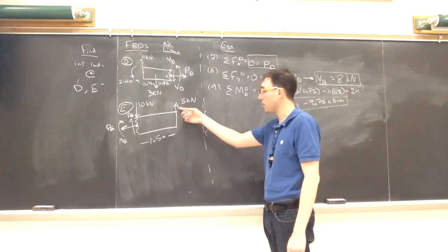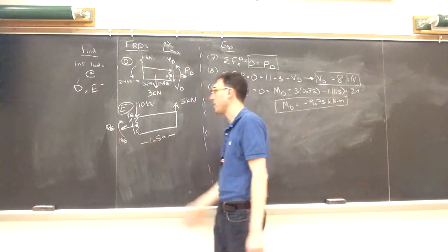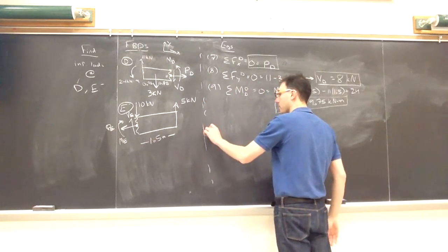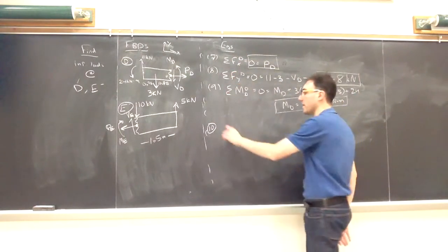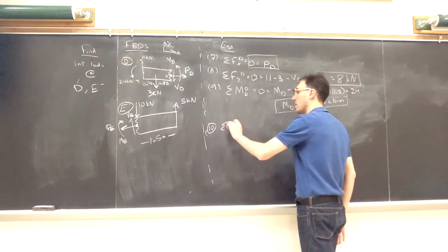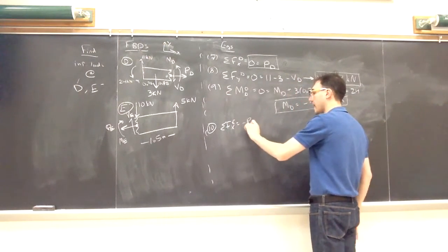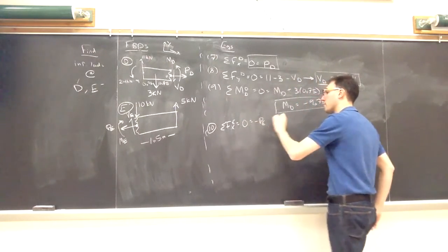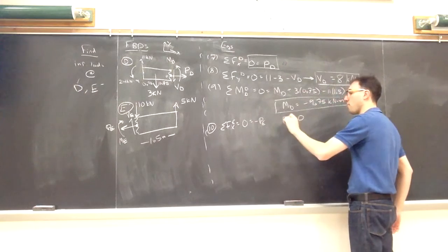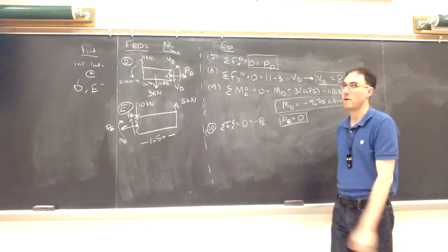Again, from step 1, we already knew that external force of 5 kilonewtons. So there's 3 things left we don't know, and then these are usually very easy to solve because every equation only has one unknown in it. So in our picture E, if I take some forces in the x, this tells me that the internal normal force at E, or just to the left of E, is still 0.